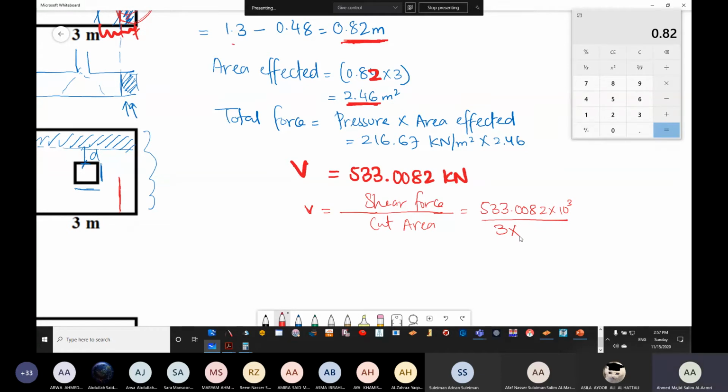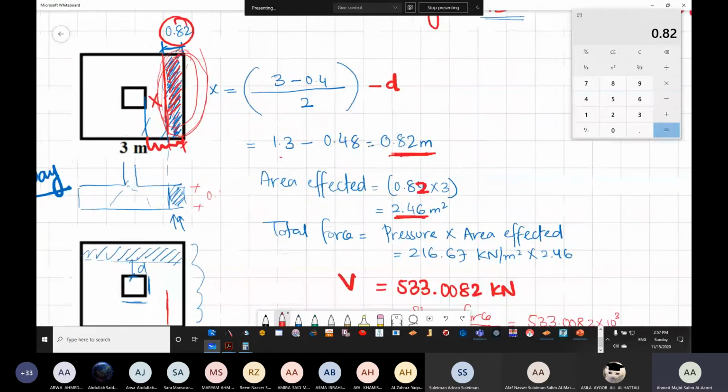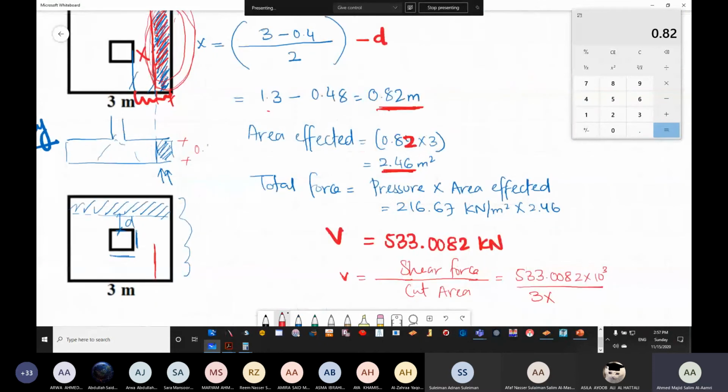Now, if I see in a section, this one is 0.54. How much is your average? 0.48. If this is 0.48, and my knife has only cut 0.2 of the depth, will the full portion go out, or do you need to cut the full 0.48?